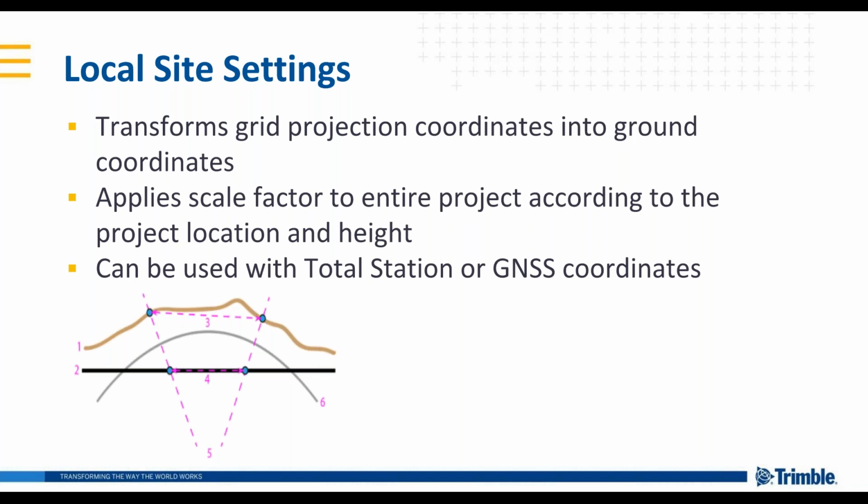They're obviously probably going to be designed with real-world distances in mind. If you're doing cadastral applications, such as surveying a boundary, you want that to be 100 meters as it is on the ground, not grid. And if you're working with point cloud data, you could have some control points in grid coordinates that you'd want to convert to ground, as most terrestrial point cloud scanning works with ground coordinates.